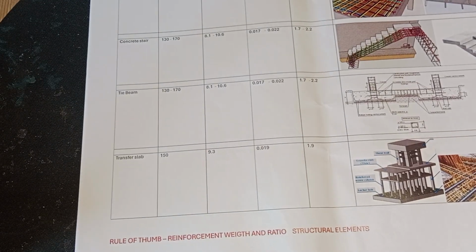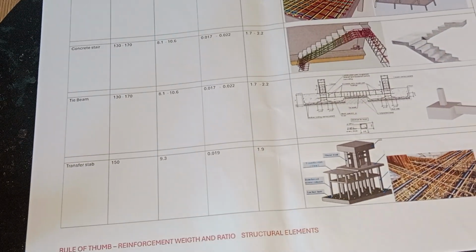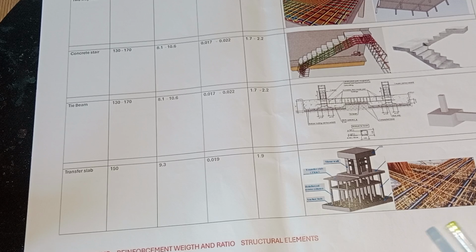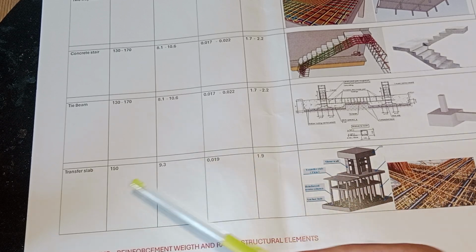The second one, the last one on this page, is the transfer slab. The transfer slab is mainly a stronger slab needed to take the change in alignment of the columns, and in general we have shear problems, punching shear problems in the top and bottom slab, and definitely we need a thicker slab. But ideally, if you go above around 150 kilograms of reinforcement in 1 cubic meter of concrete, and 1.9%, this is just a mid-range, and if you are around this range it should be okay.